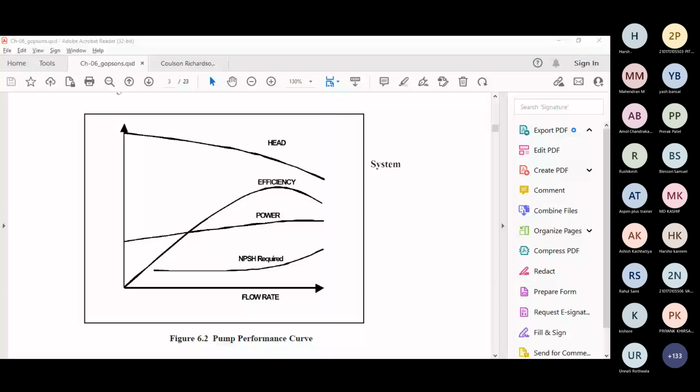So generally what happens, a PSV is given. It has become a standard nowadays to give a pressure safety valve in the discharge of a positive displacement pump, and that will go to the suction tank or source tank, or it might go again to the pump suction line. The second option is you should give a sequence to start the pump in auto. One is the recirculation line, one is the discharge line. If the discharge valve, or you can say discharge XV, is closed for any reason, then your recirculation line XV will open. So anyway, you will not block the discharge.